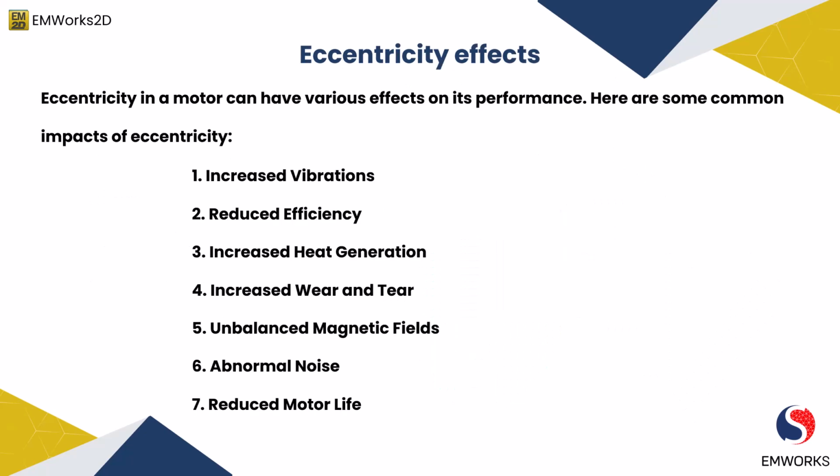Moving ahead, let us look at the effects of eccentricity. First, it could have, of course, increased vibrations. Eccentricity causes an imbalance in the rotor, which results in increased vibration during motor operation. These vibrations further can lead to mechanical stress on the motor components, affecting the overall performance and potentially causing damage.